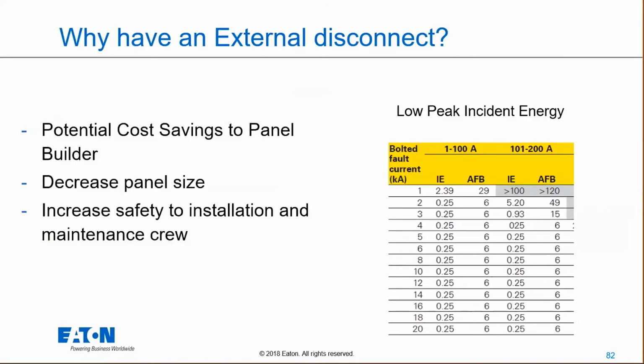The other advantage, obviously, is that if your disconnect switch is external to your enclosed cabinet, once you turn it off and you go into your own cabinet that you've manufactured and labeled and listed, once you test for absence of power, there's going to be no power whatsoever in there, right?